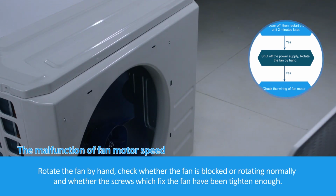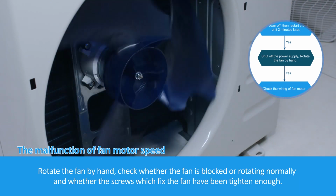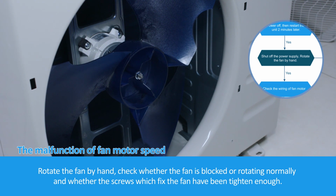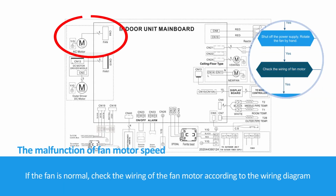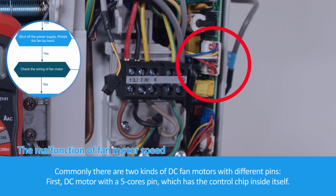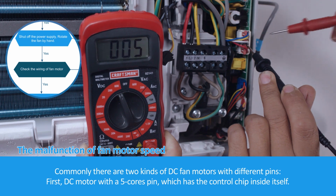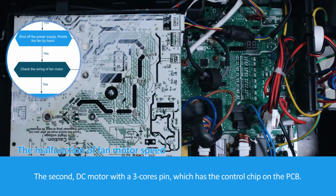Rotate the fan by hand. Check whether the fan is blocked or rotating normally, and whether the screws which fix the fan have been tightened enough. If the fan is normal, check the wiring of the fan motor according to the wiring diagram. Commonly, there are two kinds of DC fan motors with different pins. First, DC motor with a 5-core pin, which has the control chip inside itself. The second, DC motor with a 3-core pin, which has the control chip on the PCB.